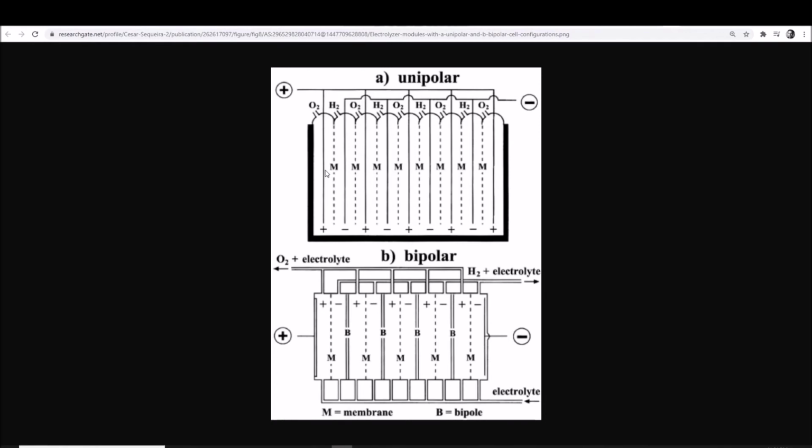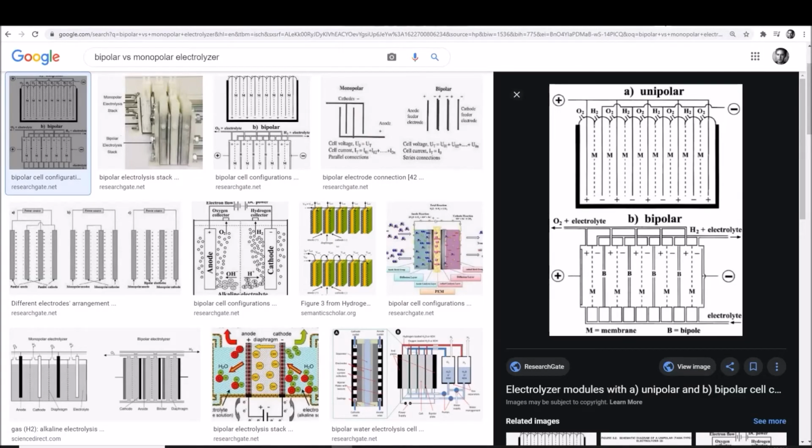Because you see, there's no connection between two electrode plates. If you have a connection, then by definition it can't be an electrode, right? It's going to be one electrode. See, they're not all stacked up against each other and connected. That would defeat the purpose. The current is actually passing through the electrolyte medium, so that's the alkaline water, and jumping from one electrode to the other, forming an anode and a cathode each time it does that. So each time the current passes from one electrode to another, it forms an anode and a cathode, and that's what they call a unipolar cell.